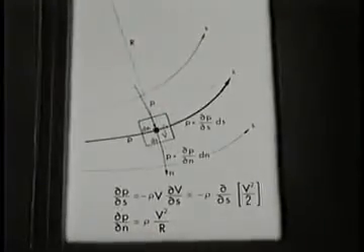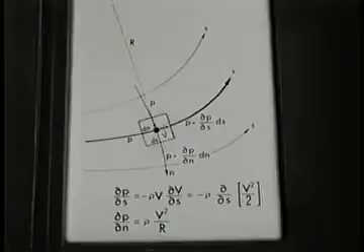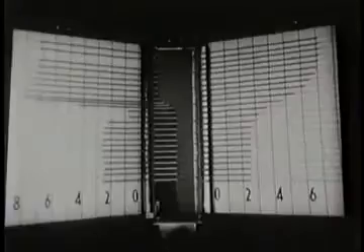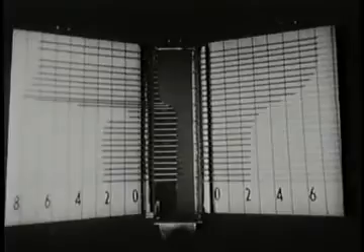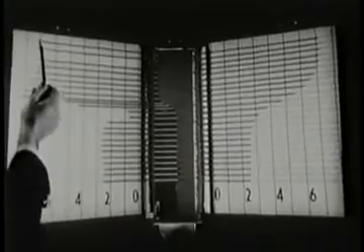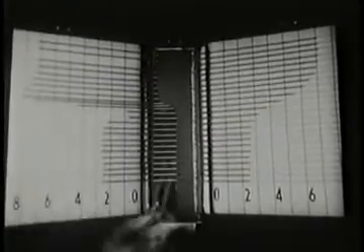Our flexible wall rig now is in the form of half of a rapid symmetrical contraction. Upstream, the pressures are equal on both walls. Downstream, they are also equal, but lower. Because of the area decrease, the average velocity increases, and, according to the streamwise equation of motion, the average pressure falls.